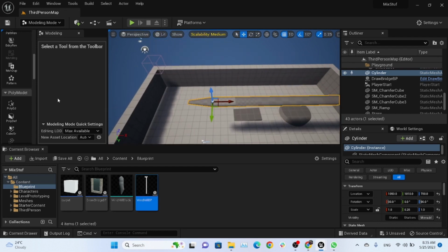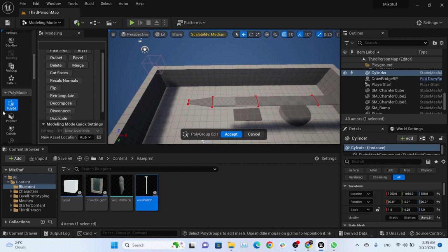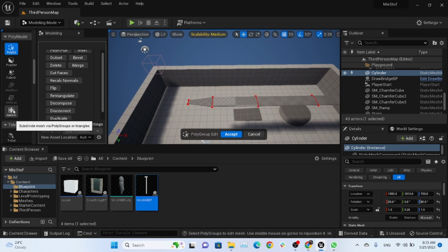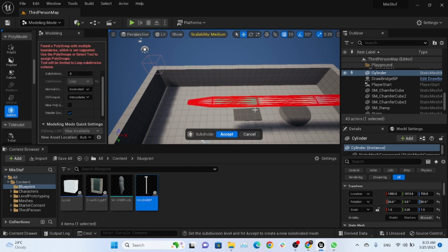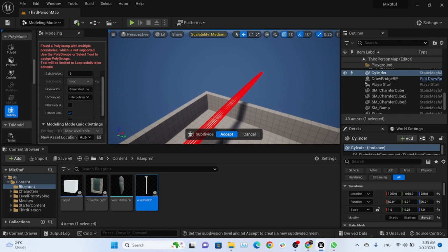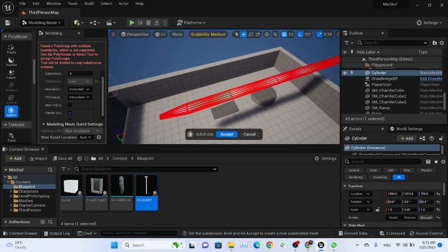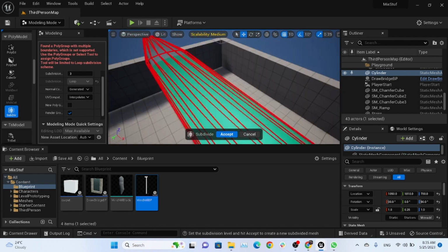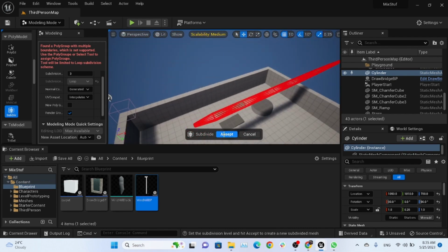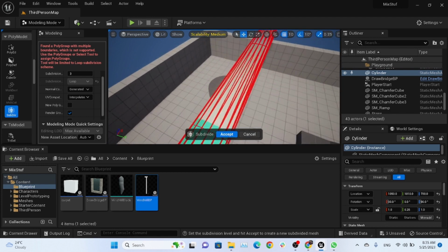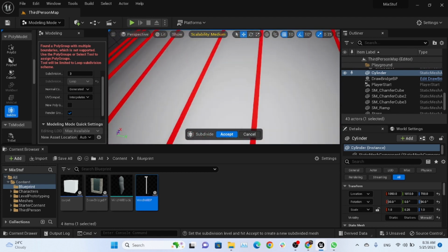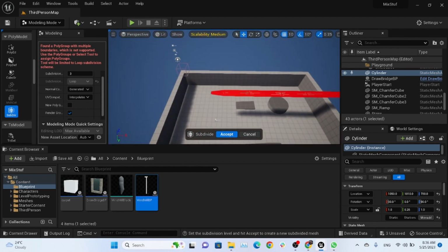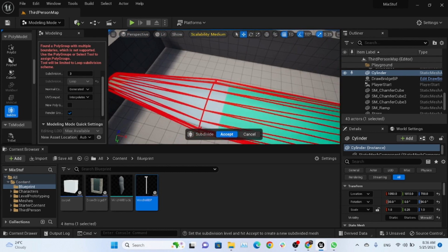As you can see, what we will do is poly edit, and from here, sorry, not poly edit, there we can also subdivide it. We will do subdivide, and it's up to you to which level you want to subdivide. The more you subdivide, the more the quality increases, so it will become high quality, with more meshes, and it will also become more difficult to compute for the computer because of the more points to calculate location wise.